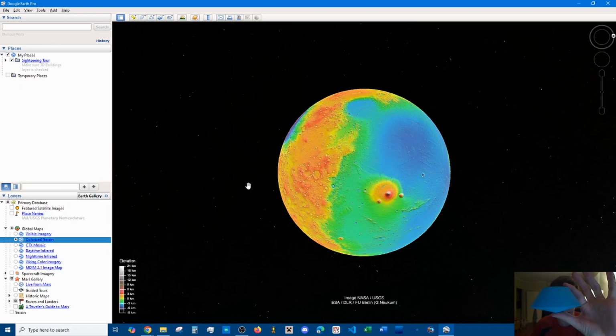This is Gen 1 Aeroshell. It is a 70-degree nose. It's not amazing, and it's got a rough diameter of just under a meter. And it is theoretically aerodynamically stable. As you can see, it's actually got quite a bit of height, and we have just one single plane here. Now, Gen 2 was to more closely model, to approximate Pathfinder's reentry, and this was to more approximate Mars Science Lab.